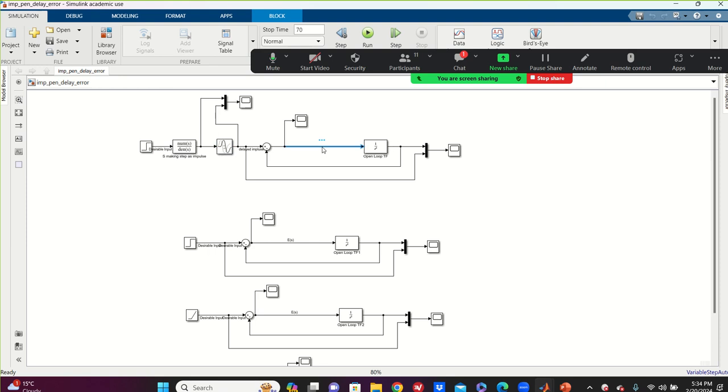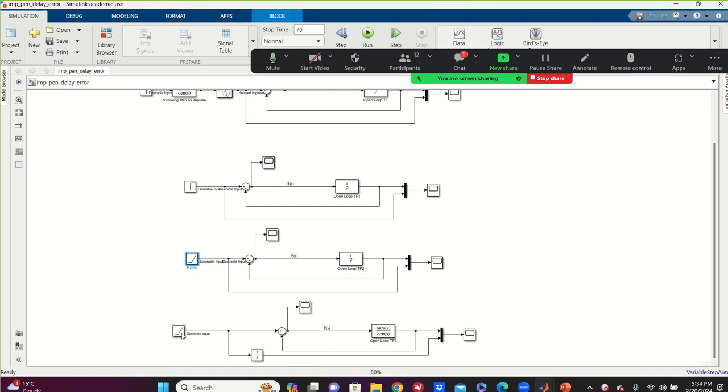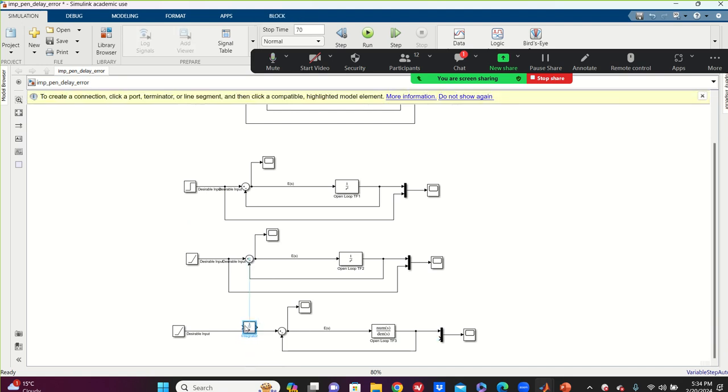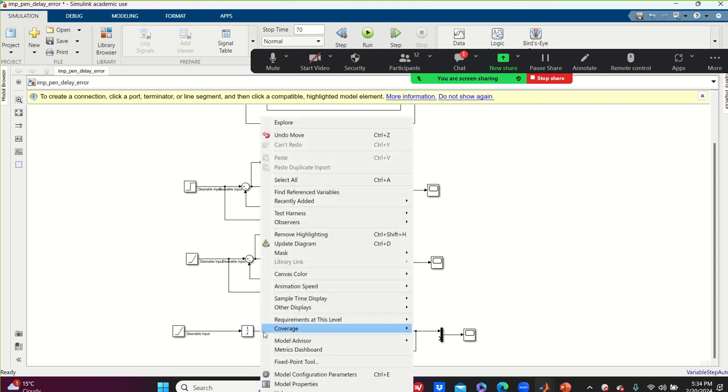I even showed you, if you put in a delay, if you have a controller actuator here, what's the effect of that. Then I showed the step, then I showed you the ramp. But I don't know why, mistakenly, I have to correct this. For the parabolic, we changed the transfer function from the previous class. You remember it, right? But I don't know why I put this here, because ramp is 1 over S squared in Laplace. So 1 over S cubed is the transfer function of what? Parabolic. So I have to put it here, guys. I don't know why I did it here. Okay, maybe I was tired.